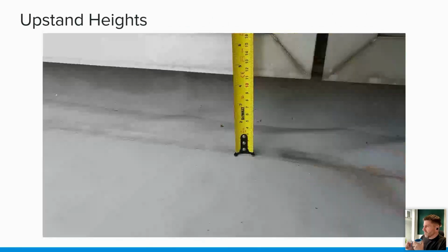We do need to be a little bit pragmatic sometimes when it comes to surveys. So this is a single ply membrane, still in fairly good condition. We're doing a condition survey on this roof, because usually when we get called to a roof, it's because there is water ingress. So we need to determine the level of water ingress. Does the roof need stripping off?